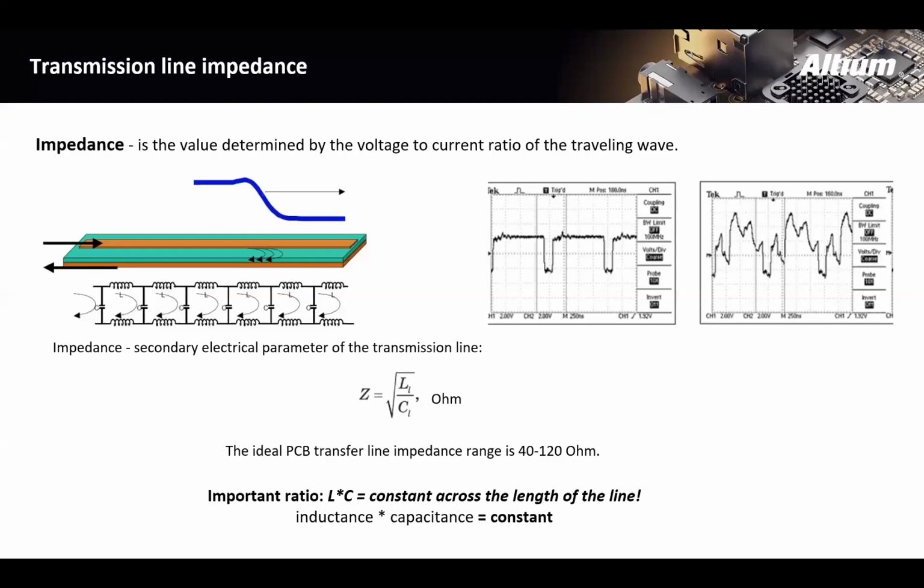What we basically have is, as the schematic says, the inductance, the capacitance, and such going down the path. Now again, at lower clock rates, this isn't a big deal, and we'll talk about that a little later, and perhaps dive a little deeper to discuss why that's the case. But one of the fundamentals about impedance, especially when we're talking about sending a signal down a path and then waiting for the return, is that the signal source impedance should equal the receiver's impedance. That's the so-called standing wave ratio, and ideally you want all of that signal that you're transmitting down that line to be received.